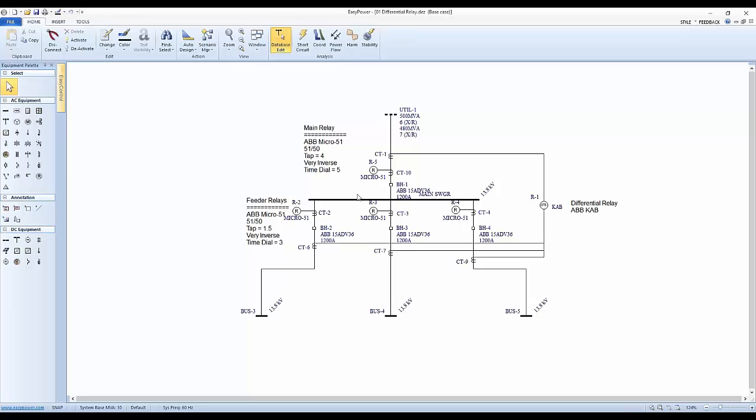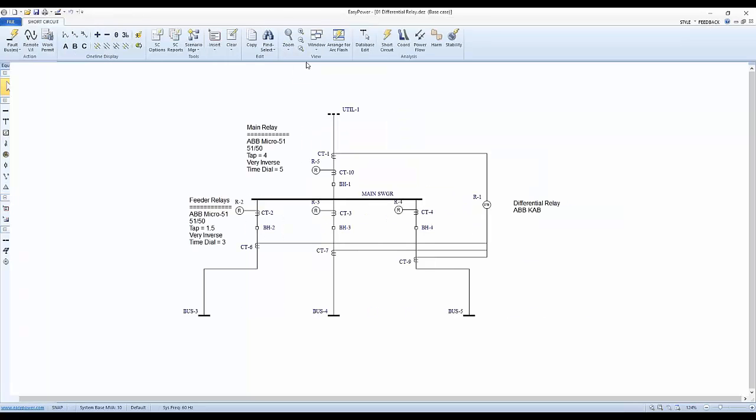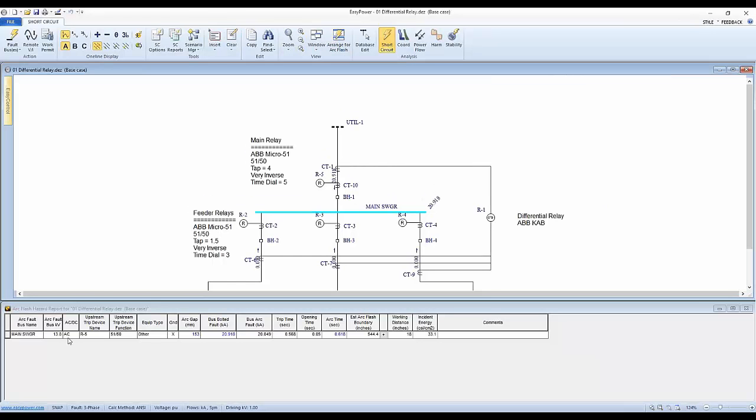And so that protects the switchgear from things like an arc flash or accidental faults that may not necessarily be isolated to any particular leg. The point being, if we go to short circuit and we fault this particular bus, and let's look at the current, and we range it for arc flash, we see that R5 has tripped based upon this fault.